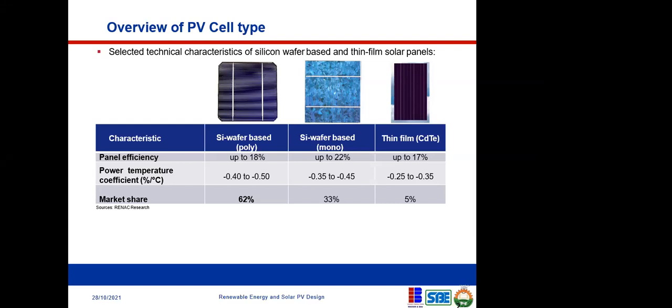I think this slide should have come later, but let me try to explain this here. Like I said, temperature affects the efficiency of these cells. So there's what we call temperature coefficient. The higher the temperature in the atmosphere where you install this PV system, the lower the voltage. It affects the voltage of the PV cell. But let me not go into that so I don't create confusion. There's a place to talk about it in more detail in a way that you can understand. But just ignore that middle line. I will talk about it later in the presentation. I don't want to lose your understanding on this.